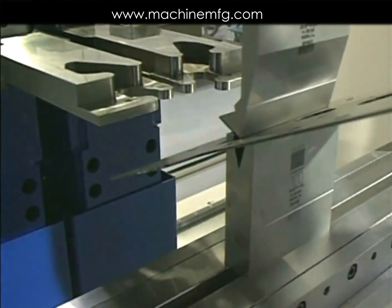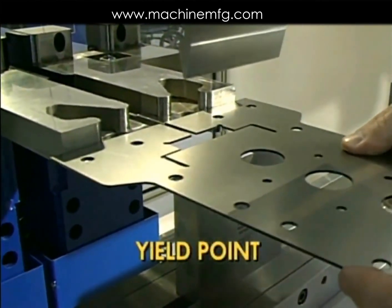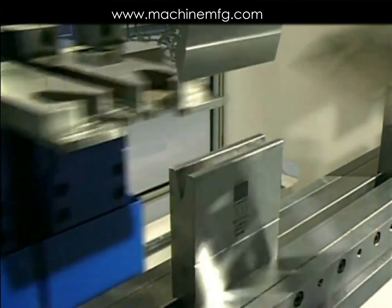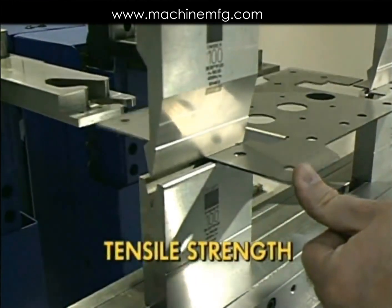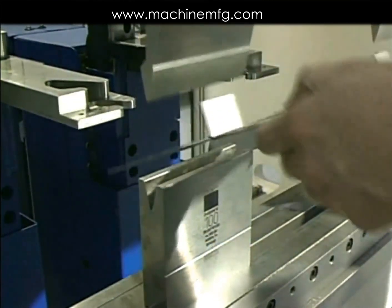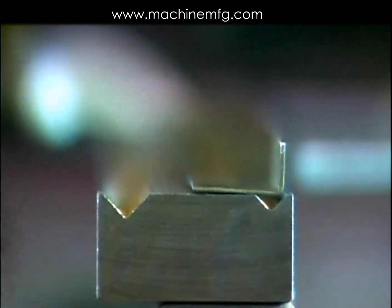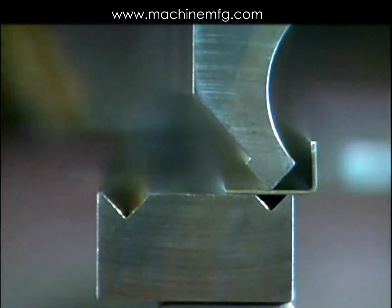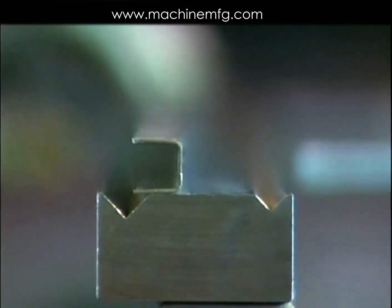Bending is a method of producing shapes by deforming the metal beyond its yield point, which is the material's capability to resist permanent deformation, but not past its ultimate tensile strength, which is the metal's ability to resist tearing. The forces applied during bending are in opposite directions, just as in shearing. The bending forces, however, rest between the material's yield point and its tensile strength.